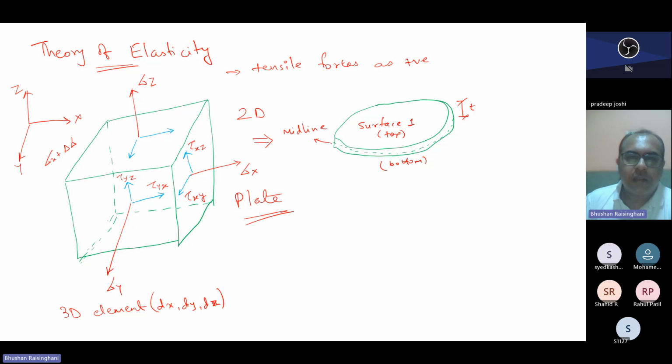So modeling thin shells as plate element, you need to check in the software or in the analysis using the differential equations how it is giving you the results. Okay. So I am talking about the plate, not membrane. So membrane and shells are different. Plate can be used as a thin shell. Okay. And this is what we are deriving. The plate is a 2D element which we are deriving the equations for.